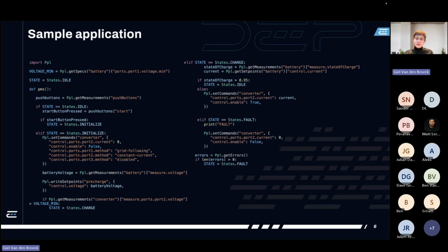2.5 seconds later, open the auxiliary contactor again. No, this is built into the operating system. It knows, okay, pre-charge, this is the sequence that it needs to go through. These are the digital outputs I should control. And the sequence is built into the software in there. That's what an operating system should allow you to do. It's an abstraction layer between low-level logic and writing your actual application.